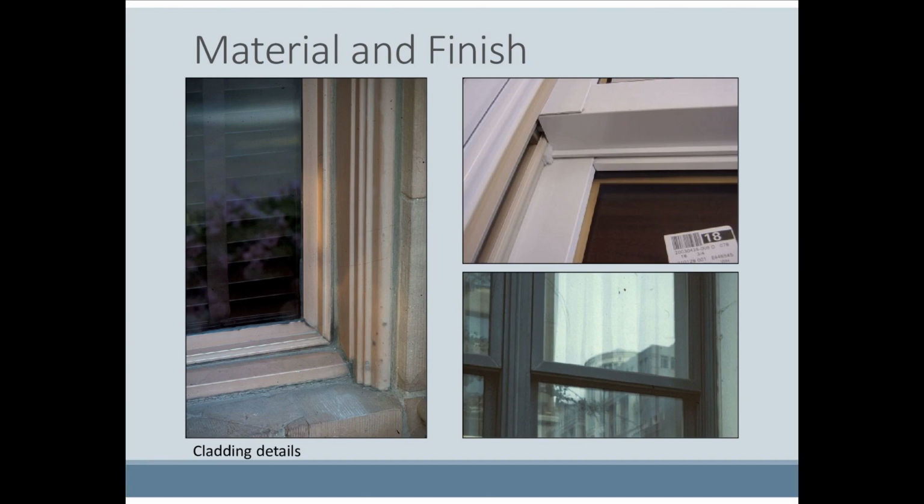New windows manufactured of substitute materials not only have different finishes, but also have different profiles and dimensions from wood windows. Wood windows are assembled with orthogonal joints and have painted surfaces. Some vinyl or enameled aluminum windows, such as these shown here, have mitered joints and overlapping surfaces. These details can give the window a different appearance and thus may not be appropriate replacements for wood windows.